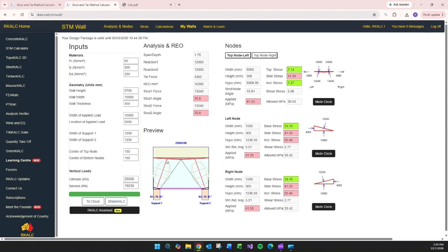So what we can do, so the height of the model is the height between the nodes, essentially, center of nodes. So if we try, let's say, top node 300, so you get, at the bottom node, let's say 250. So the model gets compressed, and that angle here is becoming like within 70. You can nominate any angle that you like for the strut inclination. And now the whole thing looks fine because we kept iterating.